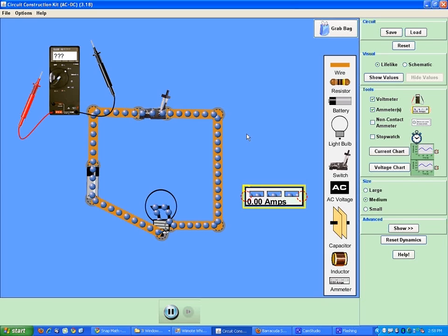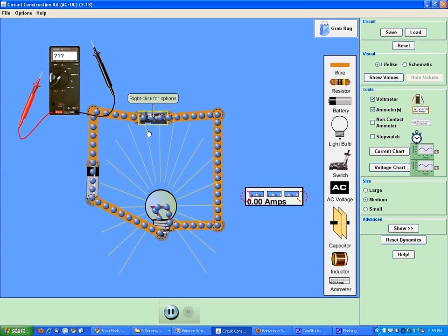Now, the multimeter can either have a high resistance or a low resistance. If I'm measuring current, you think I want a high resistance or a low resistance? Low. They don't want to slow the charges down. So when we look at putting it into a very, very low resistance, which is why we have to be careful. If we hook it up wrong and send a big current through it, we can damage the device. So make sure you measure the current correctly.